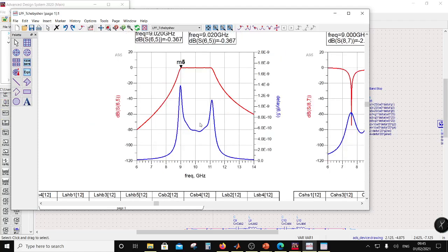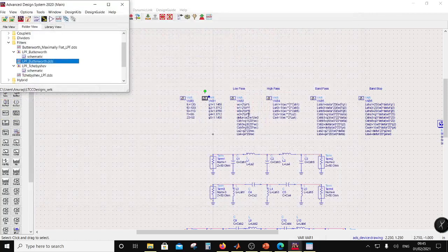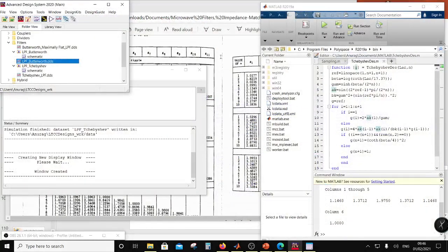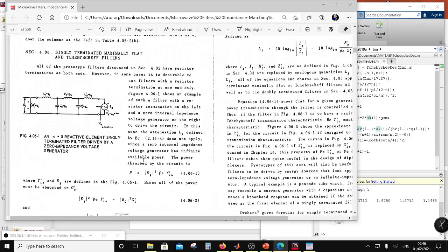Okay, so after this I'm going to do an elliptic filter. For the elliptic filter I would have a table which would be slightly different, because in that case there are more components in an elliptic filter. So this Matthaei, Young and Jones stops at Chebyshev. It doesn't do a treatment of elliptic filters. So over here, this is a very important book.